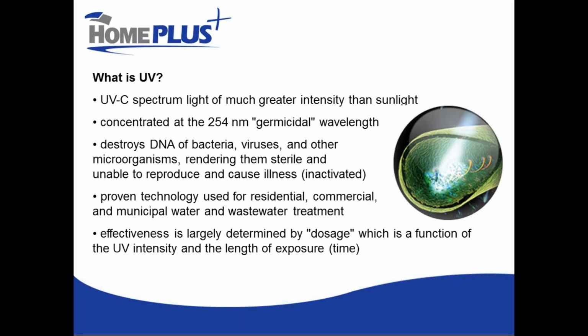The largest UV sterilizer installation that I'm aware of in the world right now is in New York State, and it treats 2.2 billion gallons of water per day. And the UV reactors, or the chambers in which the UV lamps are located, are large enough to walk around inside. So the technology is very, very scalable to larger applications.